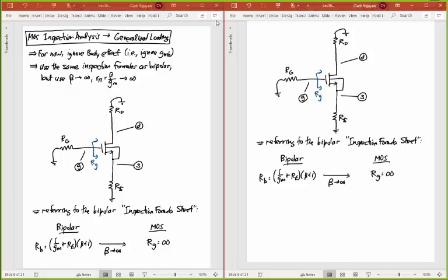That little resistance there is the resistance looking into the gate. I'm going to use the same nomenclature as I did for bipolar. This thing I'll call R big G, the resistance looking out of the gate in a generally loaded situation, and so on for the rest of these. So this is going to be R little d instead of R little c. This obviously is going to be R big D. You can see it hanging right there. And you see RS, in that case R big S. And in this direction, looking up that way, that's going to be my R little s.